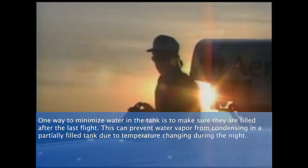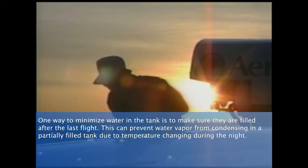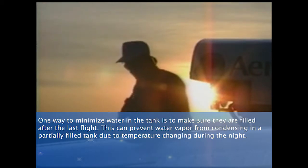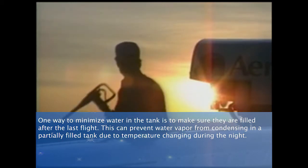One way to minimize water in the tanks is to make sure they are filled after the last flight. This helps prevent water vapor from condensing in a partially filled tank due to temperature changes during the night.